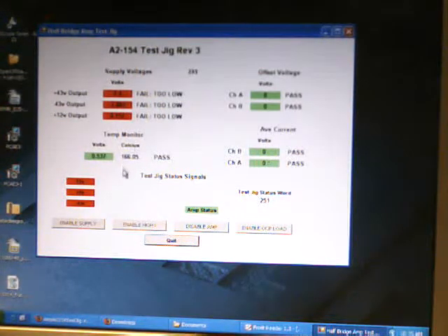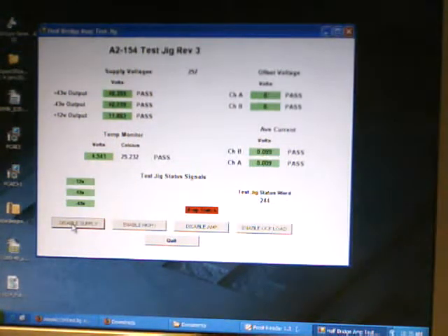Let's go ahead and turn the amplifier on. In order to do that, we turn this switch right there. As you see right away, our power supply voltages come up, and when you plug things into 120 volts AC, you get about 39-40 volts showing up right here. Our 12 volts is at 11.8, which is good. Our temperature monitor is showing that it's very cool. It's reading 4.3 volts, which is 26 degrees Celsius.